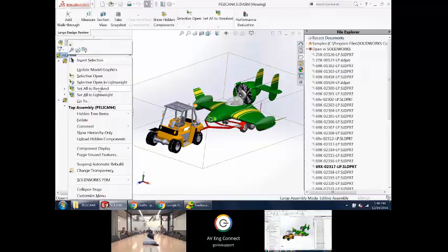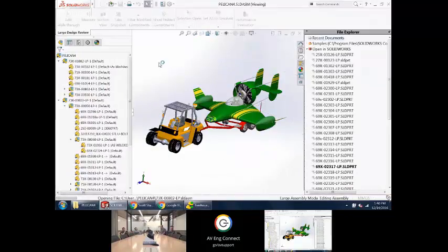And you can actually go into just regular SolidWorks inside this tool as well. If I just right click and set it to resolved, this one's going to take the longest because this is the big part. But no, it looks like large design review or the treehouse isn't really good for rearranging where things are inside of the subassembly space.